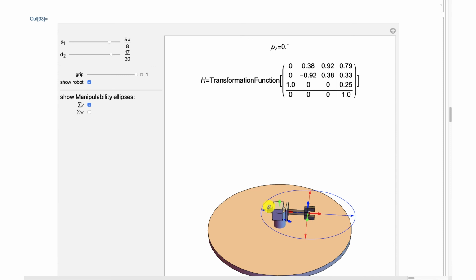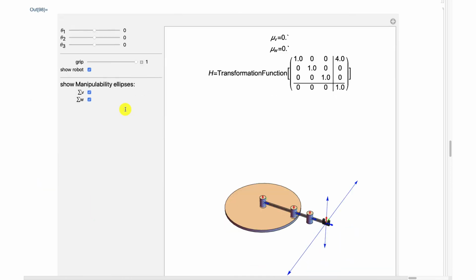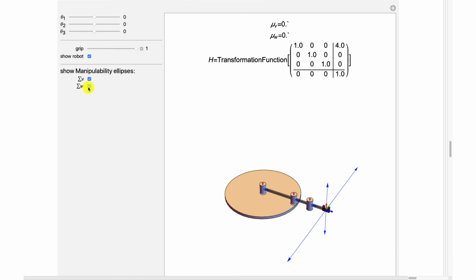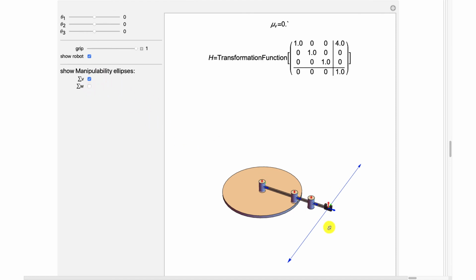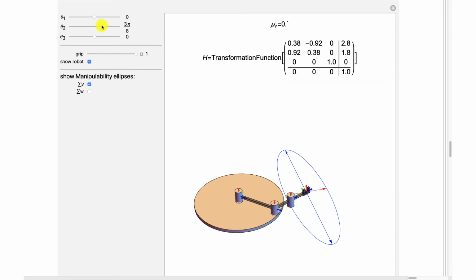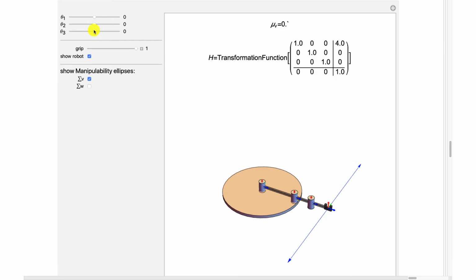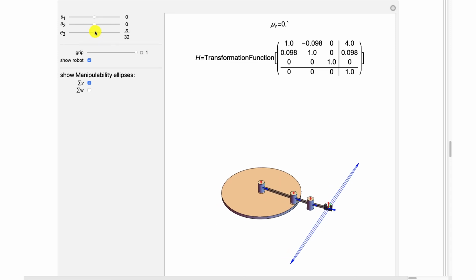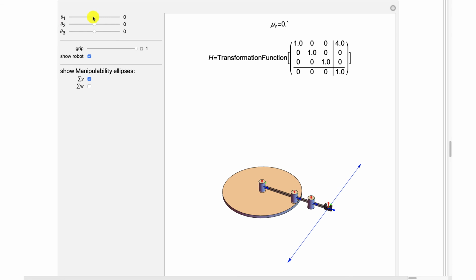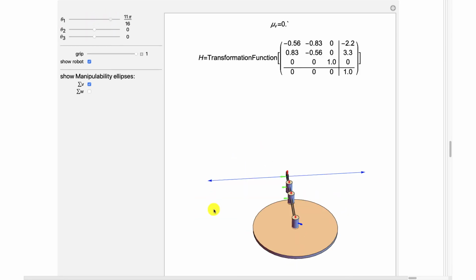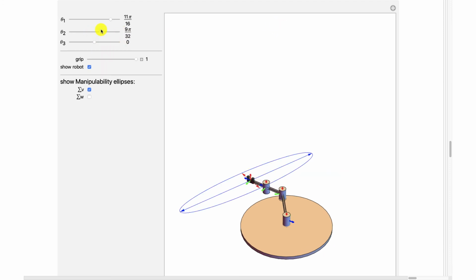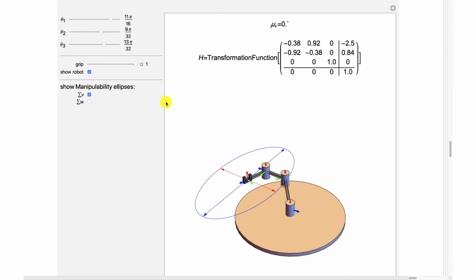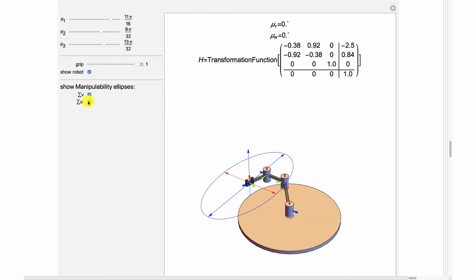Here's my three-link planar robot, the example that we had earlier in this class. It can never achieve arbitrary rotations. Right here it's in the singular position. Everybody is lined up. As soon as I move one of these joints out of there, then we're good. Move back into that singular position, and I can pop that out by moving this. You can't control the singular positions by moving your first joint. So anywhere I rotate this theta 1, I'm still in this singular configuration. You can see my manipulability measure is 0 here until I pull that out. This omega is always 0 there.